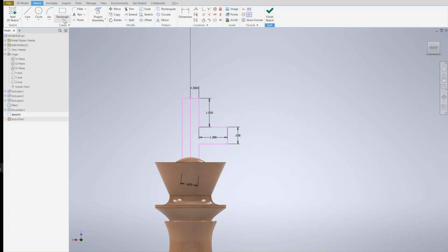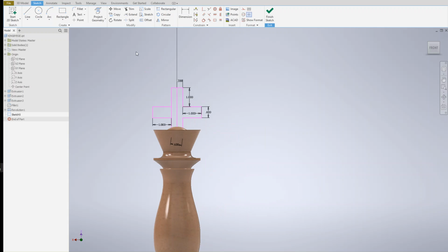All right, so we're going to need to add another rectangle here, perhaps. Okay. So this should be 1 inch, tab key, and 0.6 inches. Enter. Okay. I think maybe we can move it up a little bit. This is too close now. So let's use the move command.